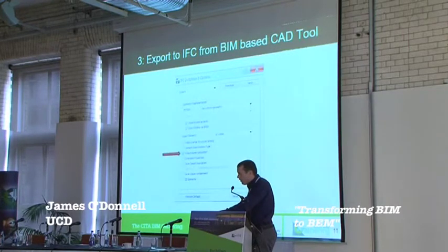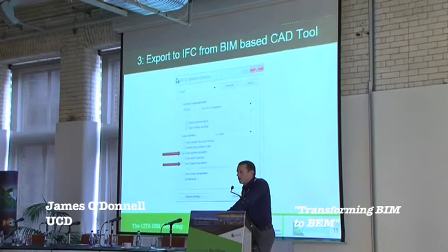The first of which is that the area volume calculation must be preserved. Energy Plus likes to work in shoeboxes and at times can mistakenly calculate the volume of a given zone. But you can override that, and what we intend to do is to override it for every instance. So we rely on the accuracy of our tool to accurately calculate the area and volume of each zone. Furthermore, we don't want to export any space boundaries, because our space boundary tool will generate the first, second, third, fourth and fifth level as needed, whereas the BIM authoring tool here will only export first level, I believe.